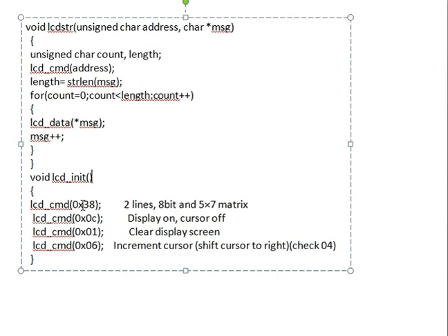It's something like in the LCD controller, the 16 by 2 controller, there is a memory address 38 wherein the service routine for this is written, which means it will configure that you're using 2 lines, 16 by 2 matrix, 8-bit mode, and pixel area is 5 by 7. So ensure that this is what the module is made for. That's what this function does.